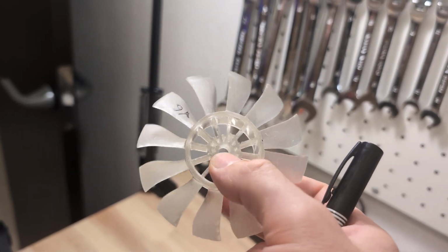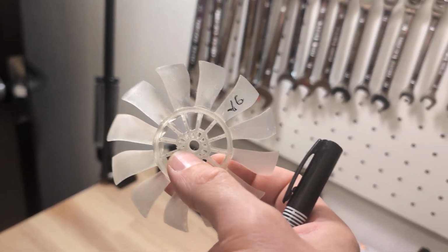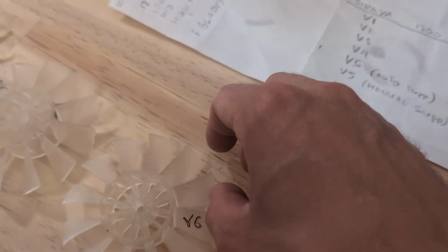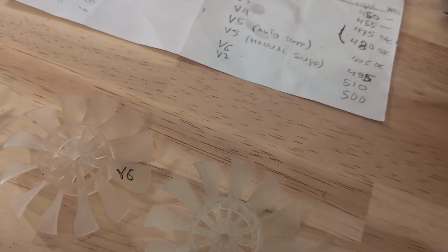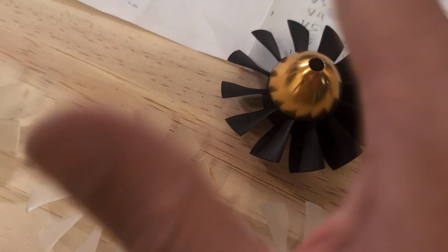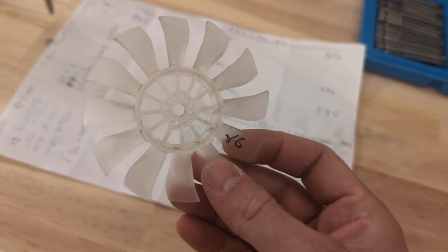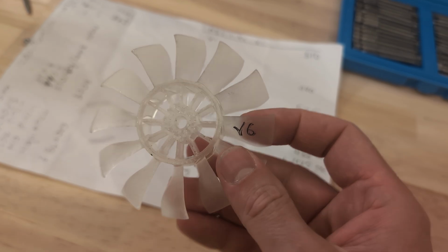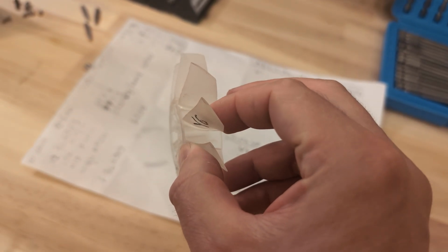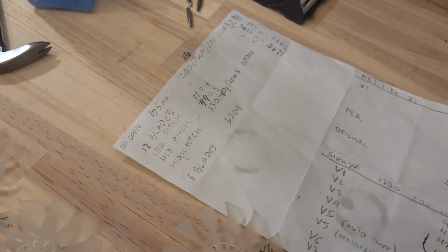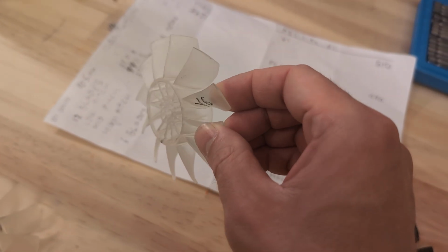And yes, I tried the maximum power. I tried to use it for the full 100 amps, 24 volts, 2.4 kilowatts. And I was getting almost the same amount of static thrust as this propeller, minus 5%, roughly. So, can you make a propeller by yourself? Yes. And actually it's very strong. Not as strong as this one, but damn, it's very close.